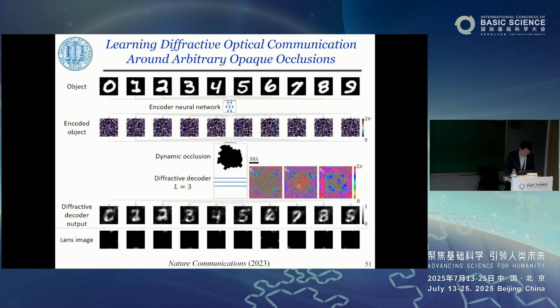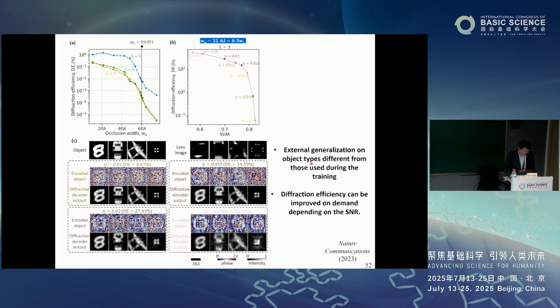The diffractive networks initially generate the spectrum profiles for the input, and the class is inferred by identifying the maximum spectral band. Simplified samples such as the digits 0 and 3 are correctly classified, as shown here, but the digits 9 and 5 are misclassified. As you can see, these initial spectrum profiles are then fed into the electronic decoders, which reconstruct the images with high similarity to the original one, even when the classification is incorrect.